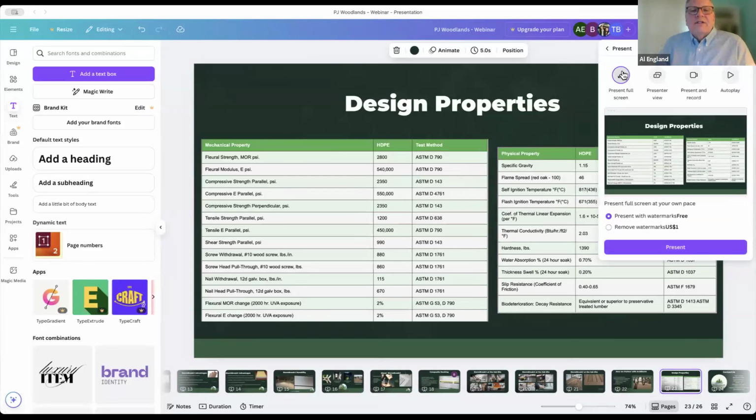Yeah, you can see that the flex modulus of this product is 540,000 psi, where typical pine or oak might be about 1.2 million. The flexural strength of this product is just short of 3,000 psi, where with wood maybe close to 6,000. So this is not a structural product. You wouldn't frame your house in Stormbreak.